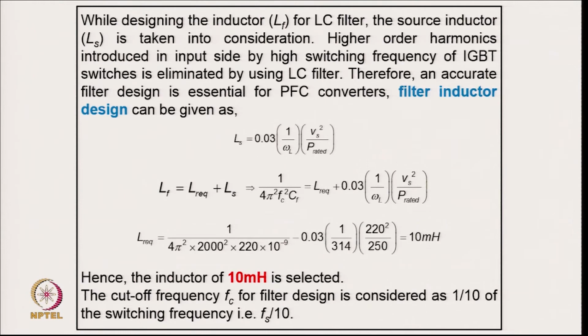Now, coming to the inductor design of this EMI filter. While designing the inductor for the LC filter, the source inductor is taken into consideration. The higher order harmonics introduced on the input side by the high switching frequency of the solid state switch are eliminated by the LC filter. Therefore, accurate filter design is essential for this power factor correction converter, and the filter inductor design is typically for source inductance with the relation.